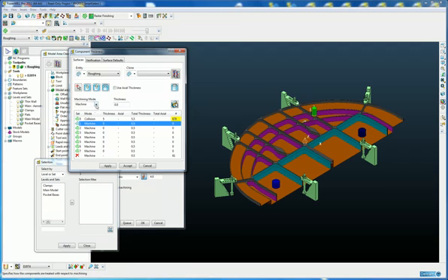I'm going to leave this set to machining, but I'm going to add an extra 1 mm on top of the default 0.5 mm, and this time I want to leave that extra 1 mm on all the flat surfaces at the base of the pockets, so all the orange surfaces.